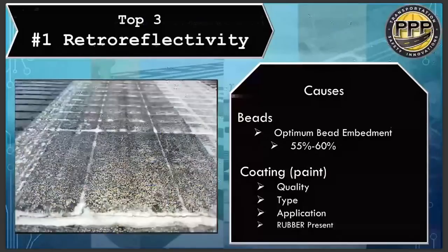But certainly, if you have spent any time on the airfield or particularly a runway, you'll know that some of the markings, mainly the runway center lines, lead-in lines, even high speed holding position markings, very often can be affected by rubber deposits. We'll talk a little bit more about some of the other contaminants, but rubber certainly can affect your retro numbers pretty quickly.